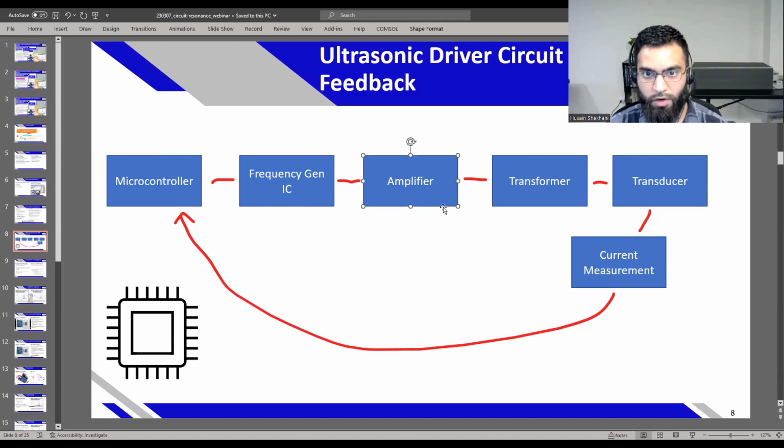So we bought an off-the-shelf audio amplifier, and a transformer which steps up the voltage and more or less matches the output impedances. We have the transducer, and also something to measure current. I'll describe this current measurement. Our microcontroller cannot sample fast enough with enough resolution, though I haven't checked how fast you can sample an Arduino analog input.